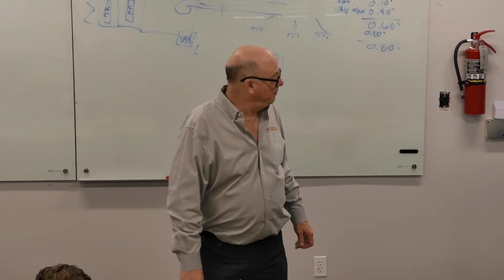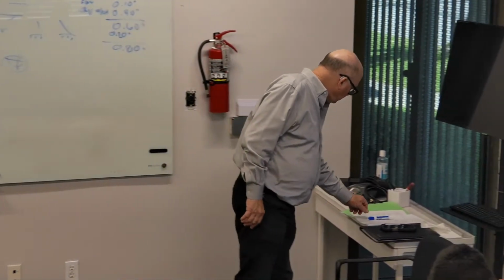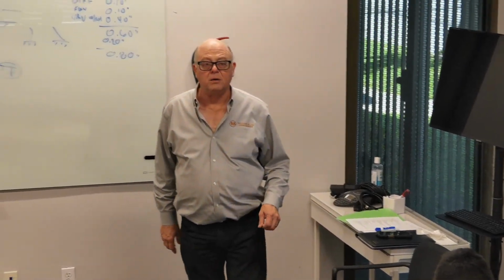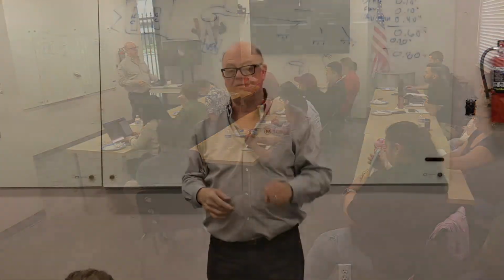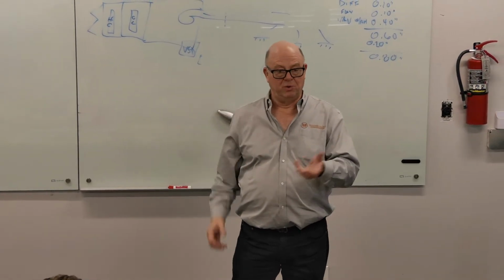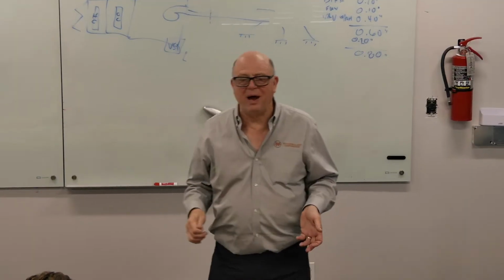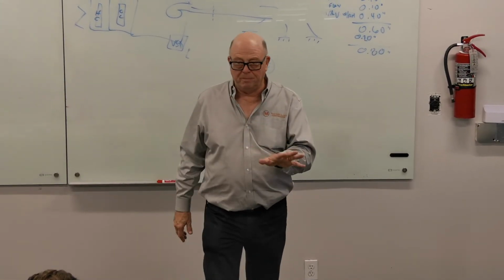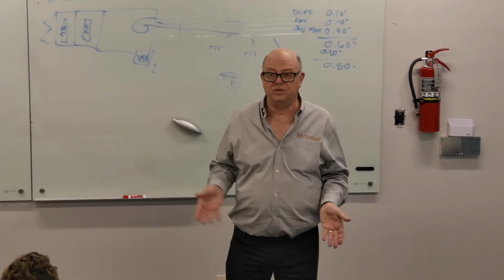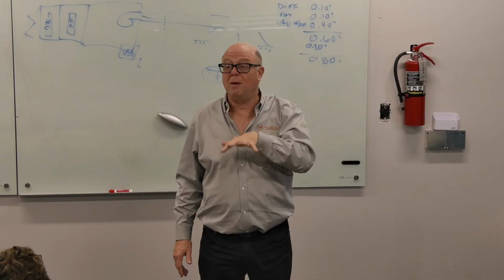That's all I got today. The next topic, we're going to start talking about duct classification and also various kinds of fan-powered boxes and when you would want to use those. Because we've just talked so far about the straight VAV box. But there's two flavors of fan-powered box that have a fan built into them. Obviously, that's going to be a more expensive box, and we have to run electrical power for the fan. So there's a cost component, but there are also places where they're very handy, where they fit. And in Southern California, we don't generally use them as often as we probably should.